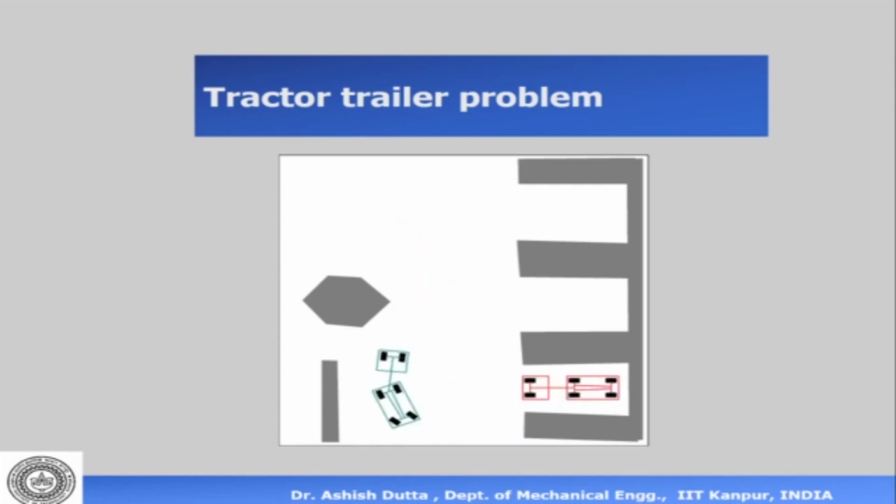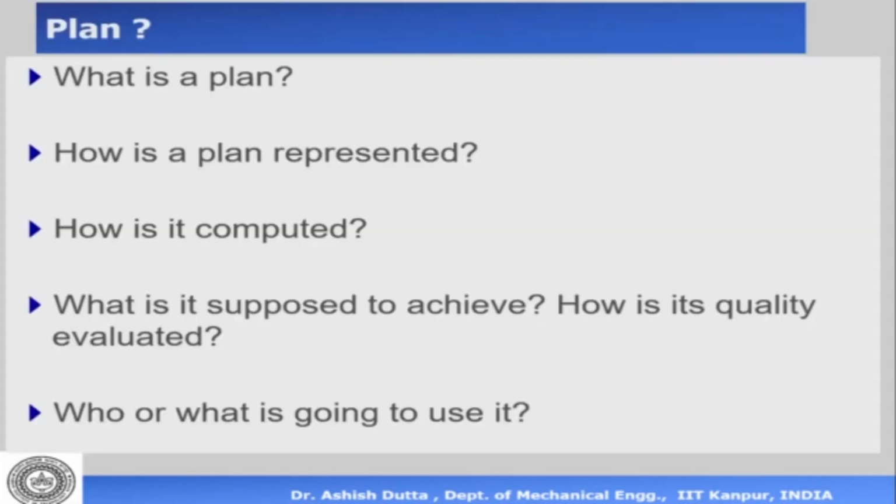This is what is a very interesting problem here. Suppose this car has to go and park here. The blue car has to go and park at the red one. Okay. So what are the various motions that are required to enable the blue car to go and park on the red car? Again, it's a trailer. The back one is a trailer. You can see it is not actuated. It can only rotate and can be pulled. Okay. So this is not a very easy problem, and we have to solve it geometrically, and a program has to solve it. It has to tell how many paths are there, if a path is there, and out of those paths, which path will be the least energy or will take the shortest distance. Okay, so these are some examples of path planning problem that we talked about.